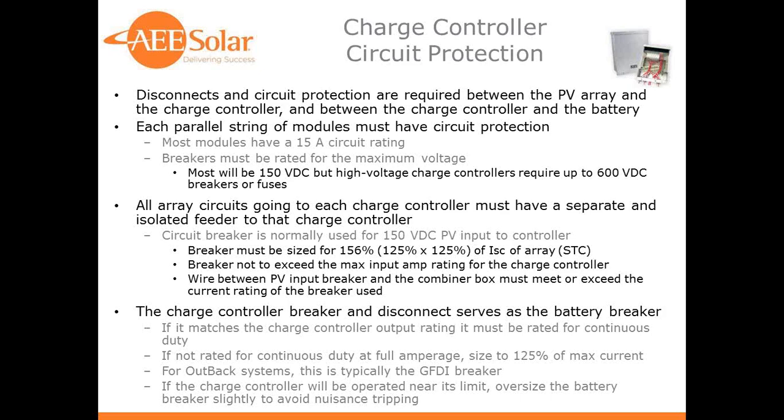I mean, if you look at say a string of 3 60-cell modules in series, well, that's 180 cells in series. It doesn't really matter that each package is only 60 cells. You're really creating a string that's 180 cells in series. And the higher the voltage, the more efficient it is to transport it through wires, for instance, and then the MPPT controller can convert that energy right down to battery voltage. I hope that answers that.